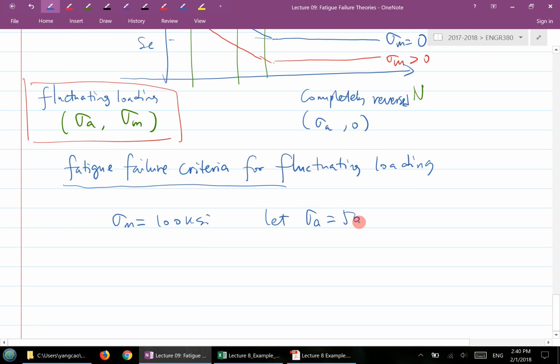You apply these 2 conditions together, and let the part start to rotate until you see the failure. But this doesn't necessarily yield a failure. If you don't see any failure, you pass beyond 10 to the power 6. Then what do you do? If this doesn't work, let's increase that to 60. If this doesn't work, let's increase that to 70, until one of the values works.